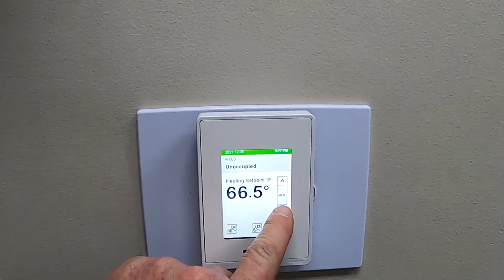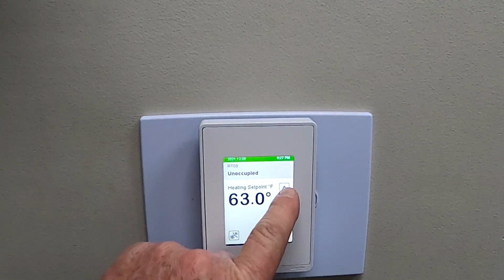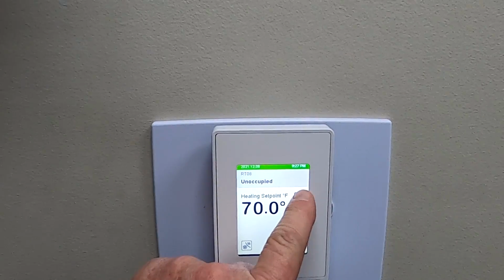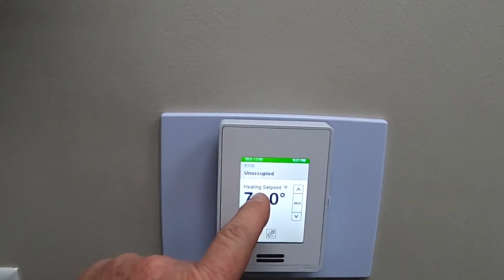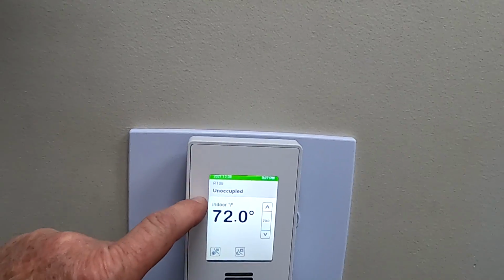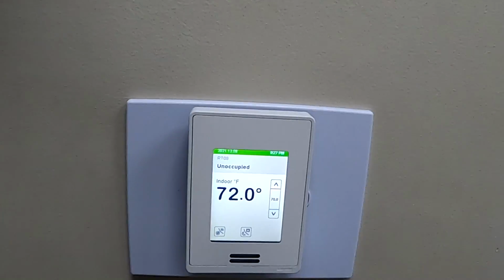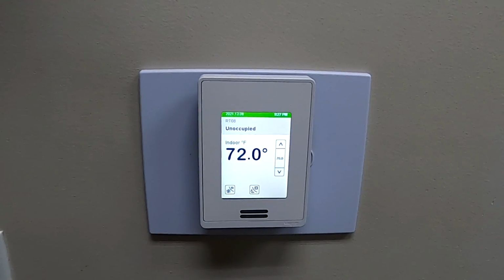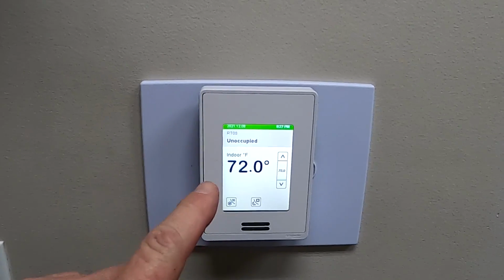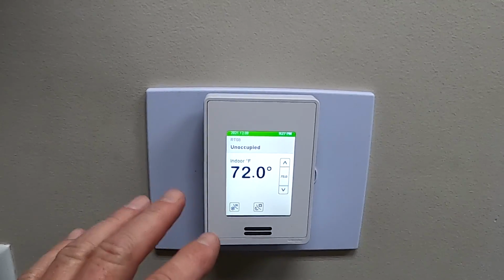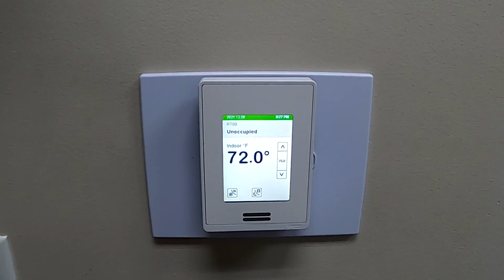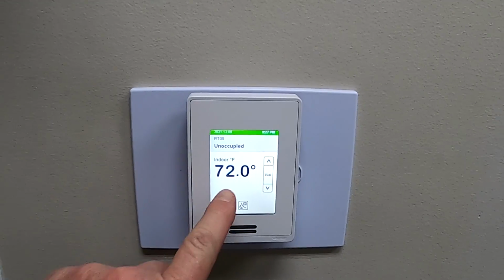Heating set point, I can move it up and down. I can raise it up, all that stuff. This one here is set so that you can't go above 70 degrees. I'll show you that in a minute. Right now, Roxanne is asleep because you can tell she's unoccupied. If I wanted to go on the front end, which I'll show you in a minute on the computer, I can occupy the system or occupy this zone on the computer to wake her up. But anyway, this is what she looks like on the front.